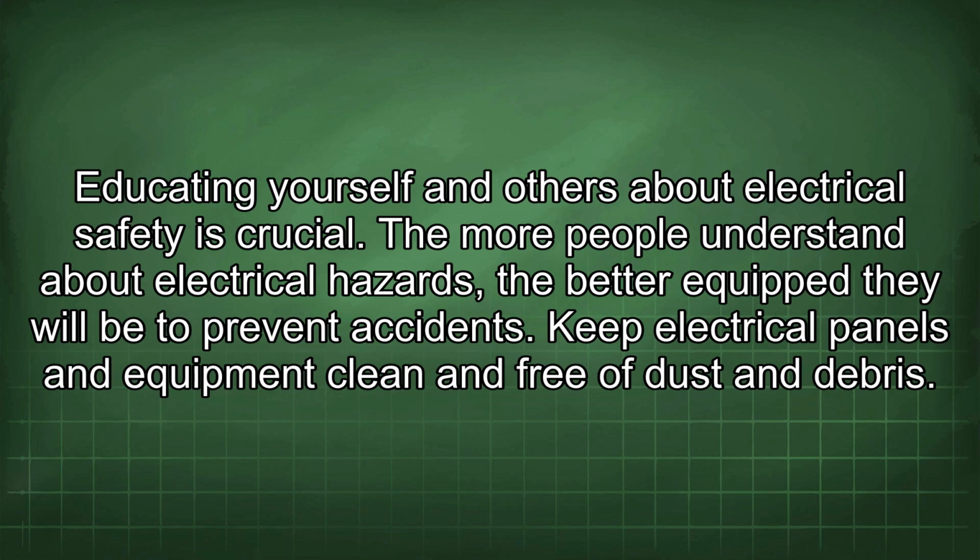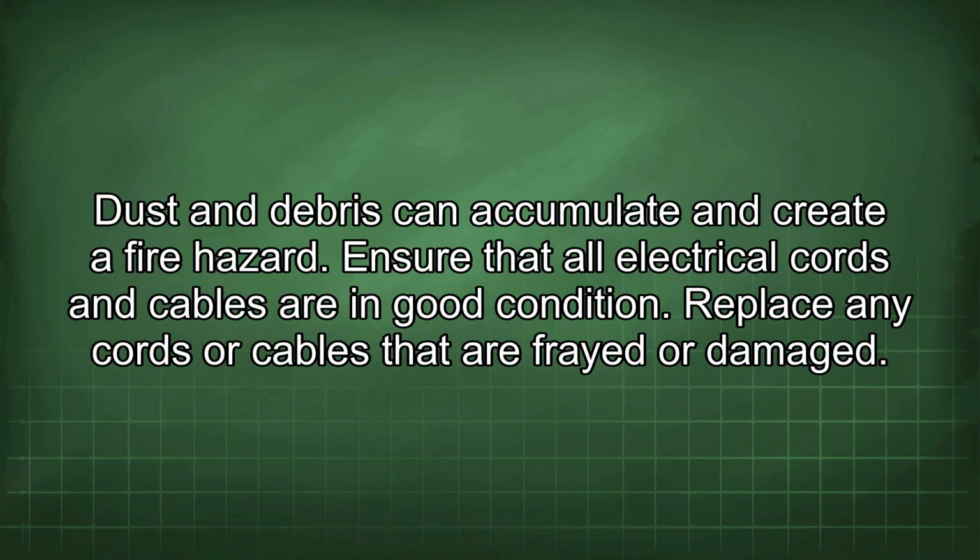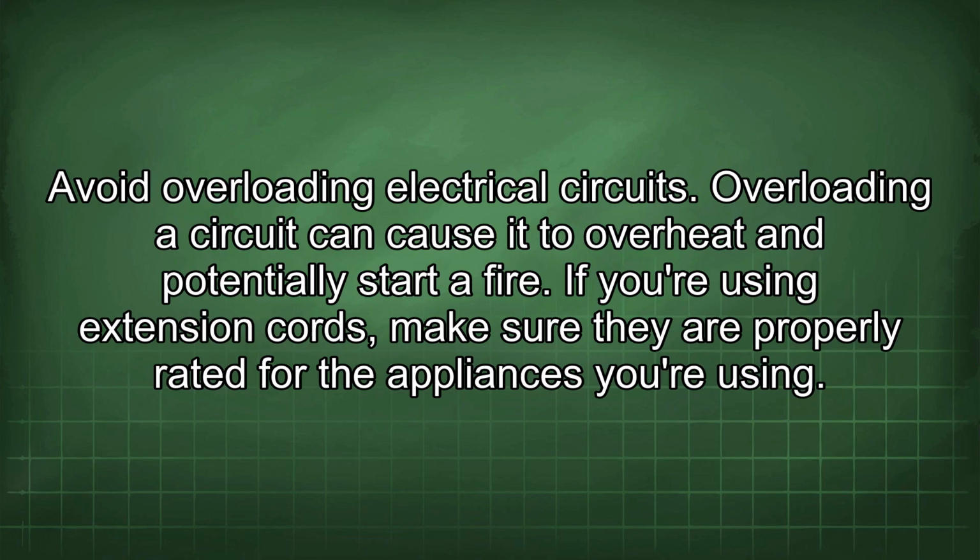Keep electrical panels and equipment clean and free of dust and debris. Dust and debris can accumulate and create a fire hazard. Ensure that all electrical cords and cables are in good condition. Replace any cords or cables that are frayed or damaged. Avoid overloading electrical circuits. Overloading a circuit can cause it to overheat and potentially start a fire.